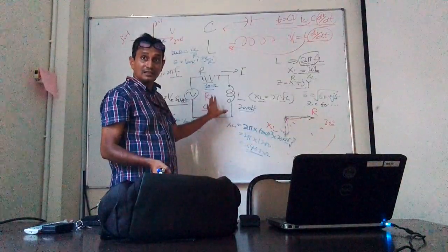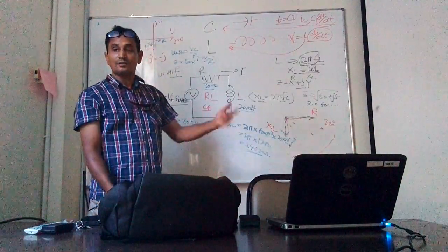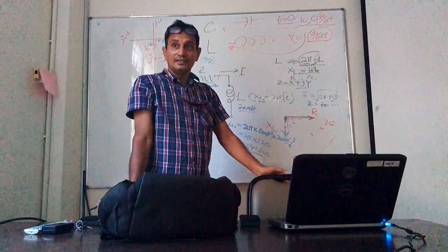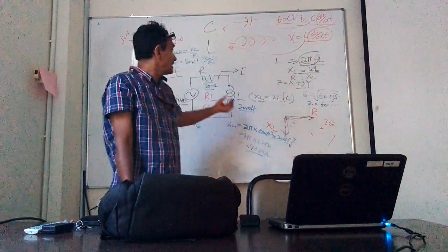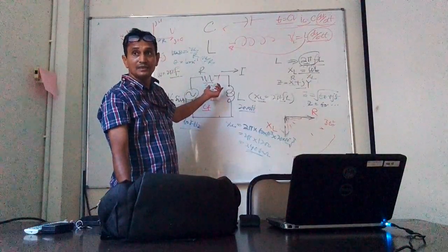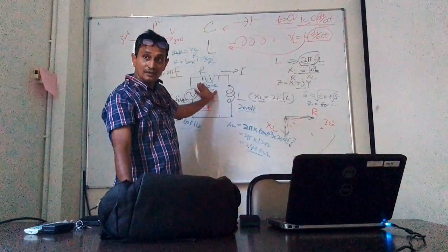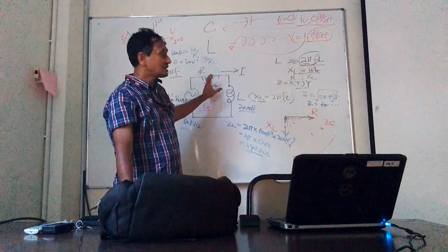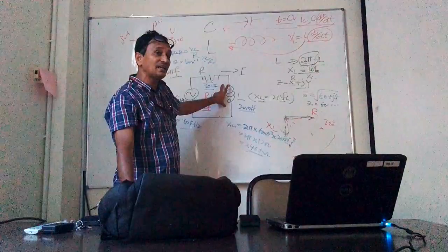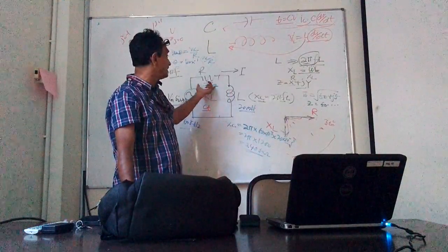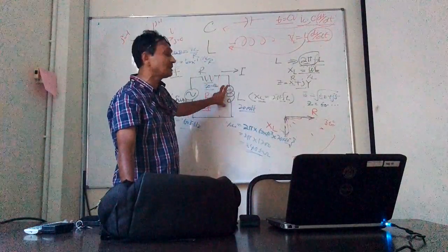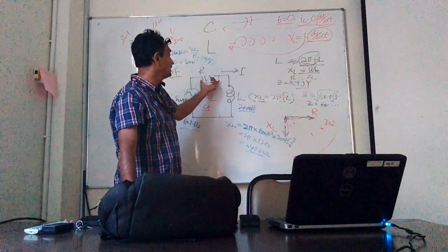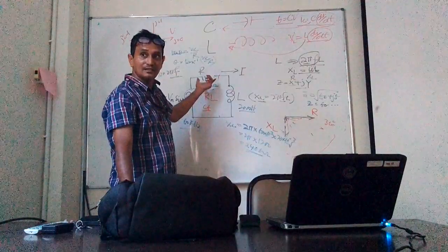If it is the inductive domain, then the current is controlled by what? Definitely the current will be controlled by the inductive reactance, yeah, because the resistance contribution is very minimum. Then should the voltage drop across the resistance be higher or lower? Almost all the impedance is here, and here is very less significant. So the current will be dominated by the reactance, and whatever the voltage is, almost all of it drops here. Here it is very little. Understand the point?